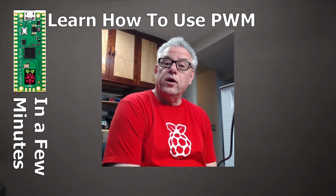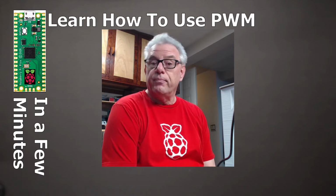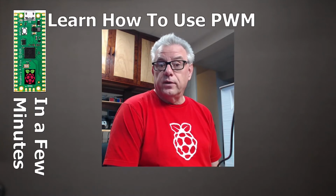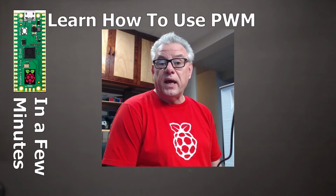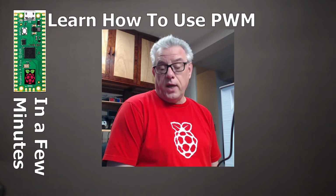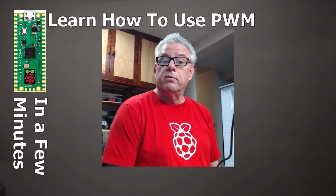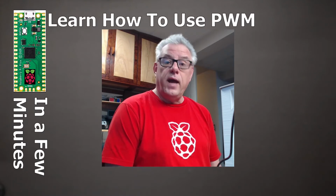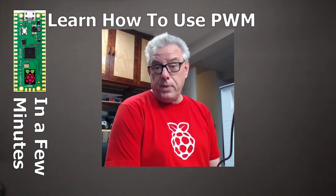Today we're going to take a look at the PWM signal, Pulse Width Modulation, on the Raspberry Pi PICO. The PWM signal is the digital computer's way of simulating or mimicking an analog output. Now, most microcontrollers and computers cannot generate an analog output, meaning a variable voltage output. Our outputs are strictly on or off and at the system's voltage, 3.3 volts in the Raspberry Pi PICO world.